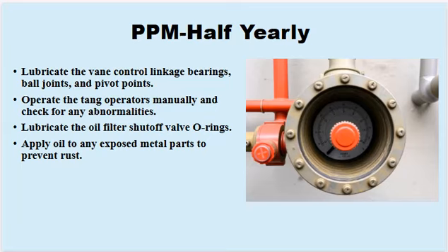The oil filter shutoff valve O-rings require lubrication to maintain proper sealing and prevent oil leakage. Additionally, any exposed metal parts must be treated with oil to prevent rust formation, which could lead to degradation of system components.